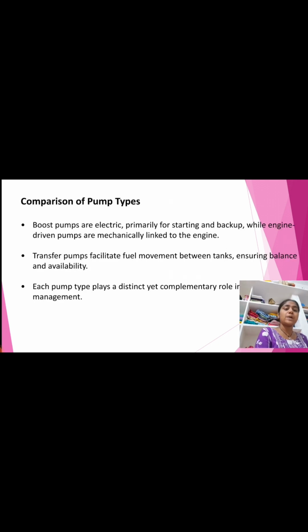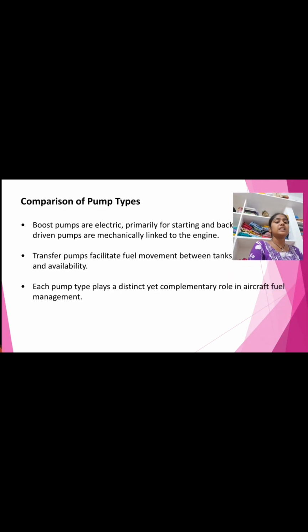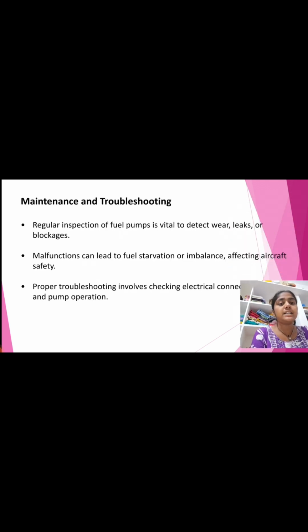Comparison of pump types. Boost pumps are electric, primarily for starting and backup, while engine driven pumps are mechanically linked to the engine. Transfer pumps facilitate fuel movement between tanks, ensuring balance and availability. Each pump type plays a distinct yet complementary role in aircraft fuel management.